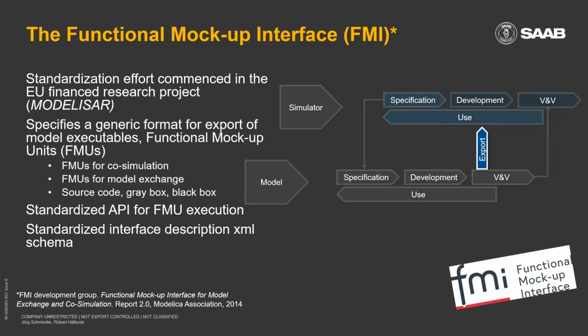FMUs for co-simulation, where a numerical solver is incorporated into the model package, or as FMUs for model exchange, where the solving of the equations is left for the integrating tool. And it provides various means of protecting IP in different ways in terms of source code export, gray box, black box, etc. FMI also provides a standardized interface description in terms of an XML schema.